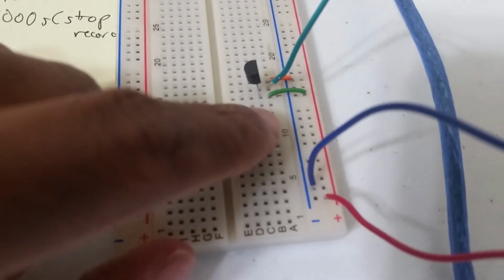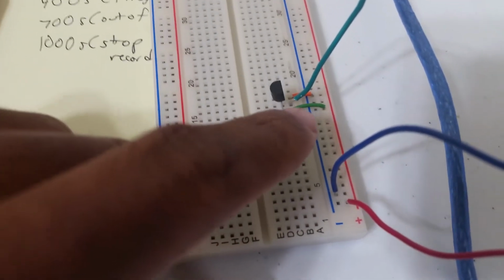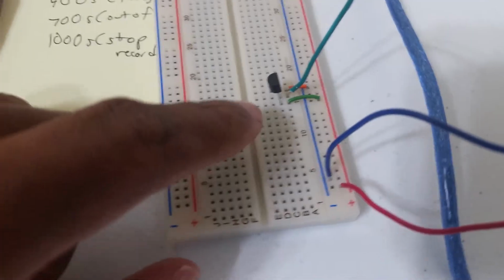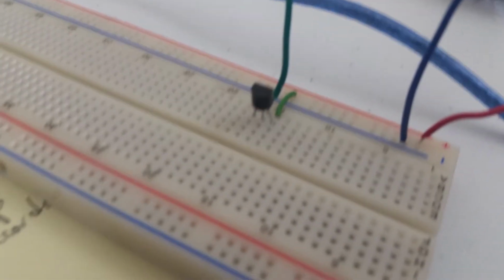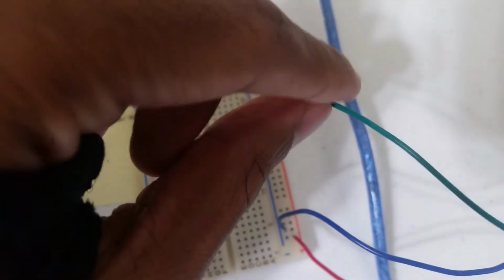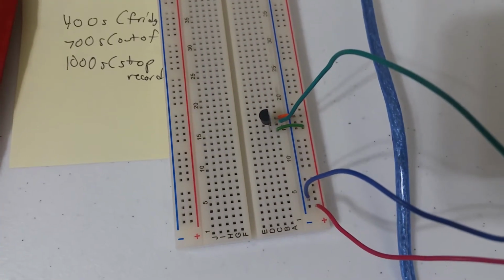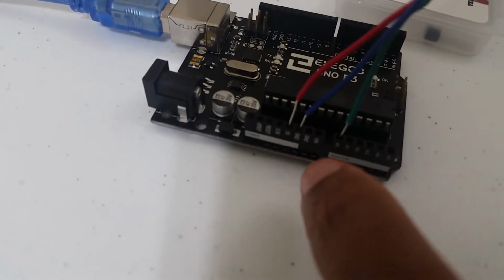And then this green wire right here is what provides the temperature sensor power. So it's connected from the positive rail of the breadboard to the far right of these three legs, the far right of the TMP36 sensor. And then the middle one, this green one right here, is connected to the middle leg of the temperature sensor. And this green one, as I said, connects all the way over here to the analog pin. So this is what's actually reading the temperature right here. Okay, so that's the hardware setup.